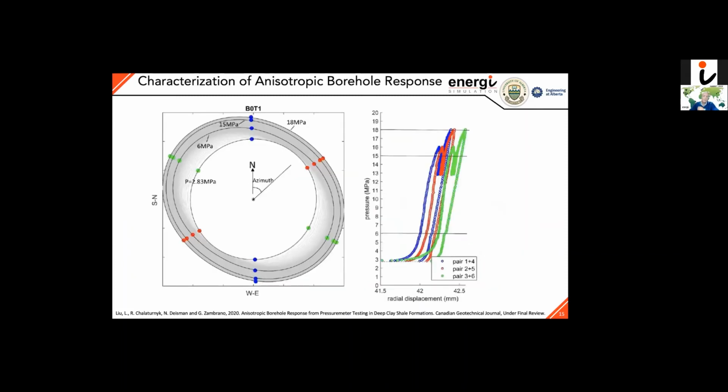And so what we did was, we did a lot of work. This is a lot of Lang's work initially and some other stuff. You worry about tool anisotropy, eccentricity, everything else, you correct it. But you can generate these maps that during expansion, you can generate elliptical expansion maps that allow you to actually describe anisotropy, and it's used in the inversion techniques for in situ stress.